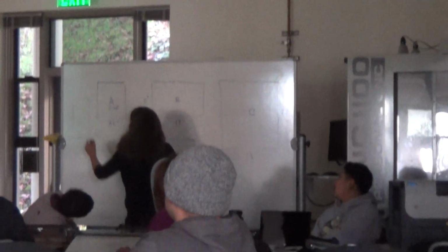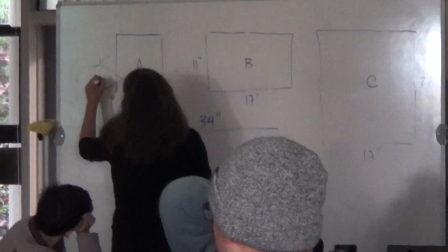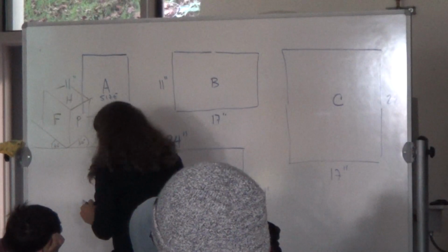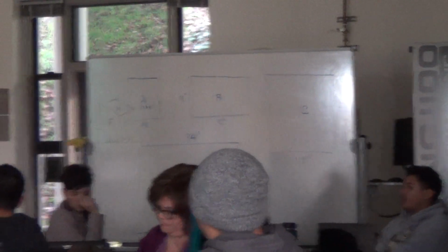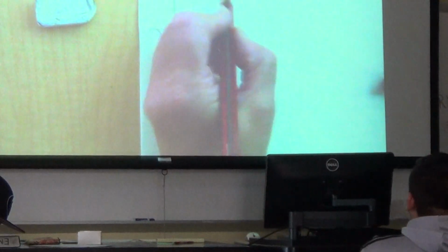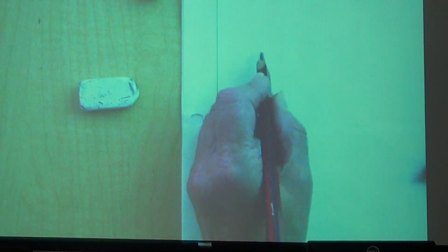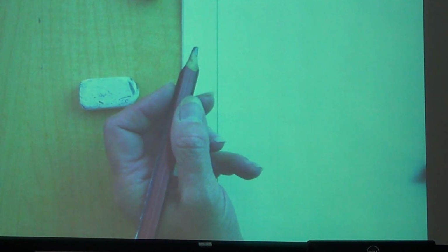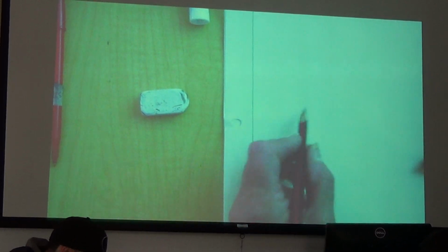Front view. And then here's my profile, and then my horizontal. So I'm going up 30 degrees. We can estimate. In this case, if you're using engineering paper, you just go up one box and over 3. 3 to 1, 3 to 1, 3 to 1. That's really 33 1/3 percent, but it's close enough for this class for 30 degrees.